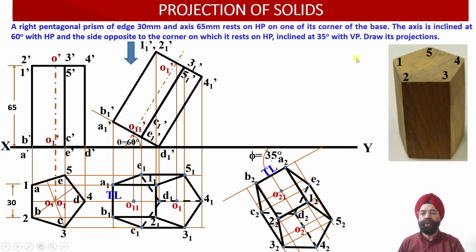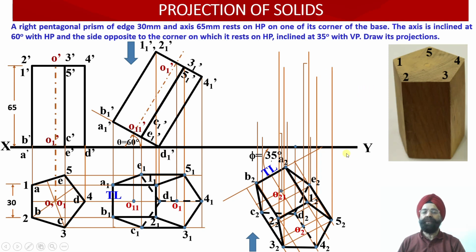we are required to evaluate the front view projections corresponding to this oblique prism over here. So how will these projections be evaluated? Please check, as the observer is going to look at this prism from this side. There are 12 points available over here in the plan projection view. From all these 12 points, we are going to draw the vertical projector lines, extending them up to the elevation projection view.